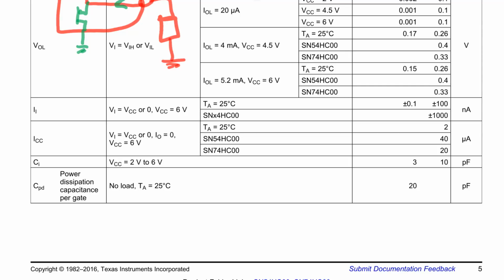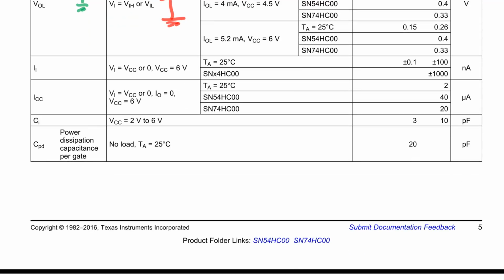Generally the die itself is not going to be at an elevated temperature because you're not dissipating any power or anything like that. So really, like 2 microamps is, if you're designing a low power widget, you might say 5 or something like that, perhaps. Of course, you can characterize it yourself, but they don't provide any further characteristic graphs on these things, and they don't provide any typical figure as well. They only give you a maximum figure.